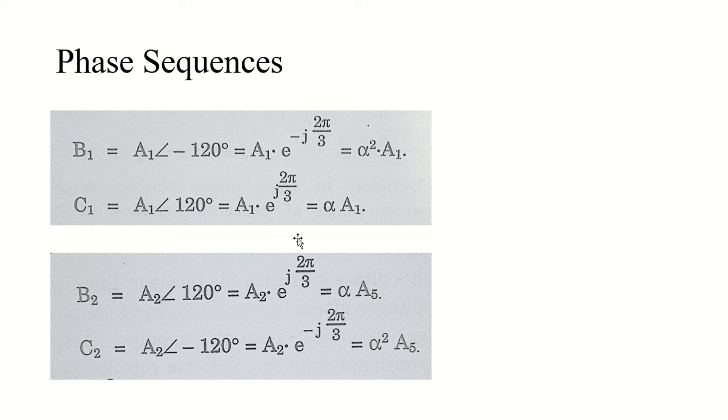So whenever you check your phase sequence and it is negative, there is a possibility that an unsymmetrical fault has occurred in your system. Again here as well, these three phasors will be negative phasors, and they are 120 degrees apart from each other, and the magnitude will be equal in all three of the phasors.